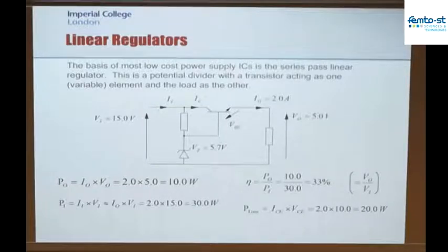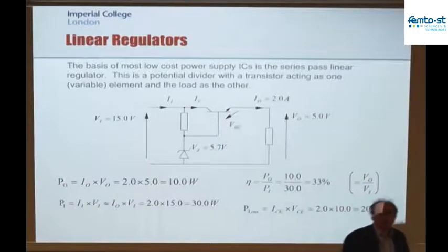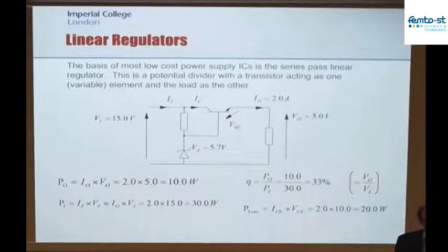Perhaps a slightly different argument in certain circumstances where I might already have high efficiency and I'm interested in getting the efficiency from maybe 98% to 99%. It doesn't make much of a difference in terms of the runtime of the system, but it might make a big difference in terms of the thermal dissipation of the system, how big the heat sink needs to be, and how I cope with that thermal management problem. And certainly, if I'm building a very small system, I want the system to be light. Efficiency will help me make it light because it means I can get away with a small heat sink.